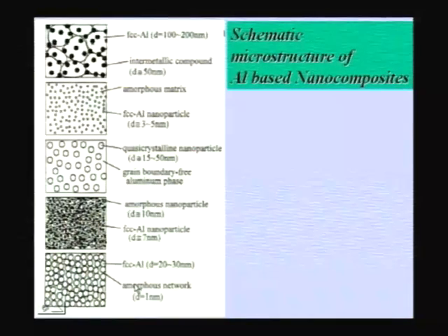This can also be possible if you are cooling the liquid very rapidly. During this process, if alpha aluminum can nucleate as fine grains as dendritic alpha aluminum, the interdendritic regions are the liquid phase that you have. If these interdendritic regions are very small, and you are cooling it very rapidly, this liquid at the interdendritic regions can become amorphous if the cooling rate is sufficient, and if its composition is sufficient to give you a good glass forming ability.